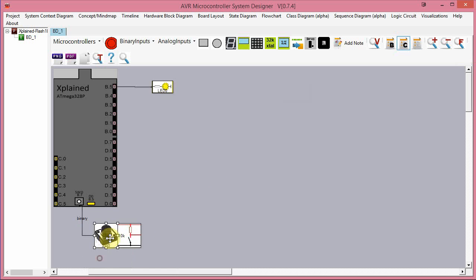And you'll see that we have a switch and we have an LED. So the actual LED is here, but it's connected to port B.5. This is B.5 up here, so that's why there's an LED on the drawing here, just so that we can visualize it and see what's happening to it. The switch is on B.7, which is actually down here. So that's been added to this point of the diagram. These are the other connection points which are on your board.